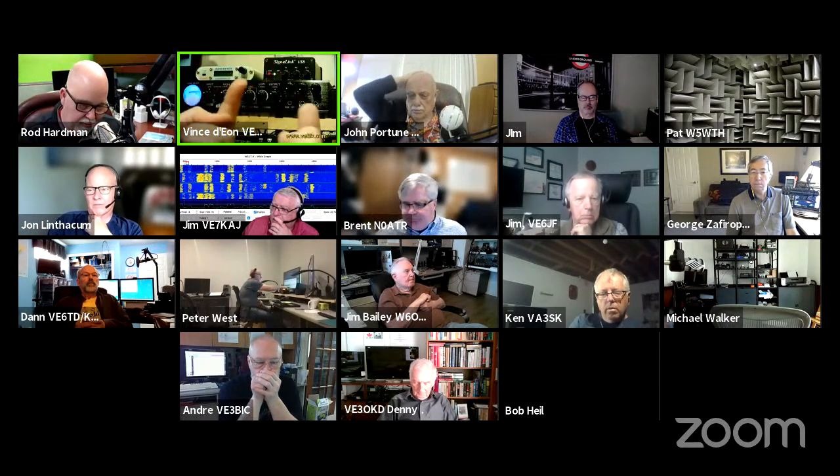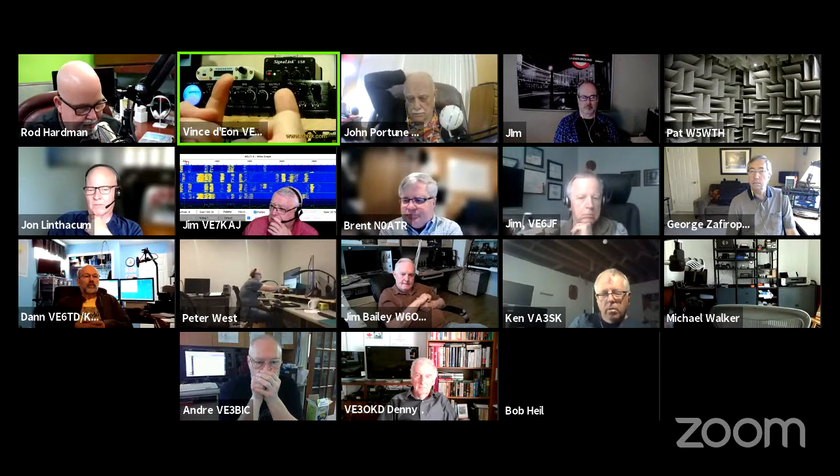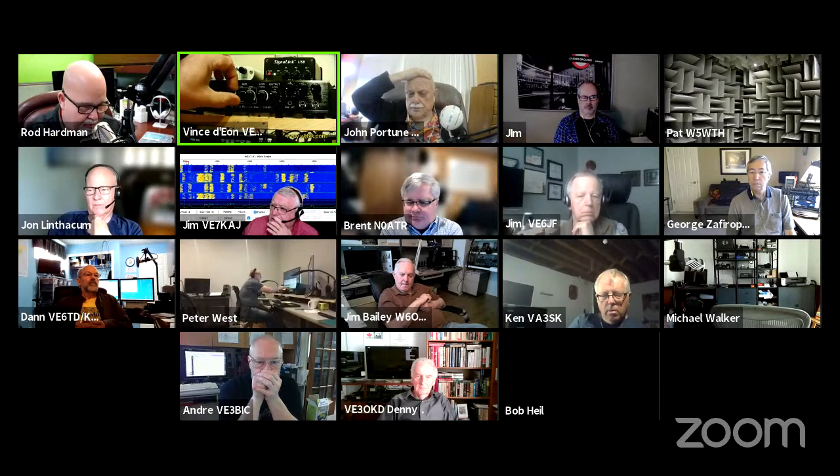All right, so I'm going to set the parametric back to factory settings. I'm going to turn down that output a bit so you can hear me as I talk, and then I'll turn the output back up as I bring these frequencies in and out. So at this moment, I've set it to be flat and in what Heil considers to be the default position that most of us hams want to use. Remember, we're really dealing with those pieces of spectrum that are between 300 and 3500 hertz that we want to hear, and that sweet spot for voice is around 2.5 kilohertz, 2500 hertz, right?